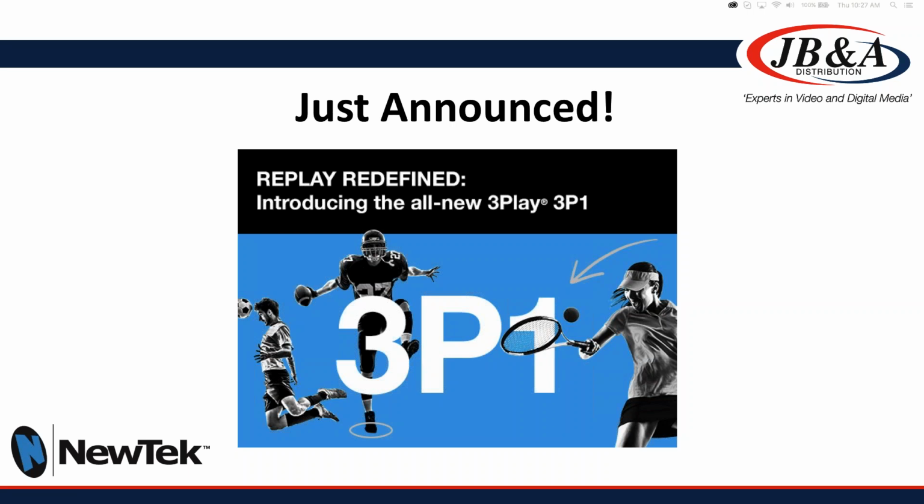This is a 4-input, 2-output replay system that's full NDI. So it can bring NDI in, NDI out. Our previous replay systems only had NDI output. So this really is the other half that people have been asking for actually quite a while, of when can we bring NDI in to a replay system? Well, this one does it. It also supports 1080p 60 video format, so it's a higher frame rate video.